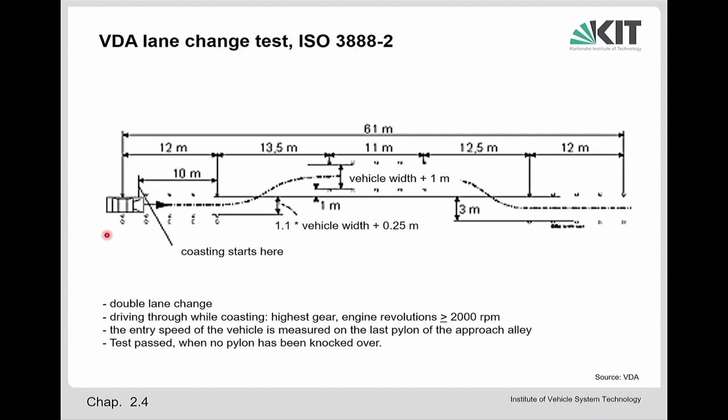Then, at the end of this, if the spring is completely compressed, there is an end stop. This is a rubber element. If the end stop gets in contact with the car body, the deflection of the wheel stops abruptly, which gives an extra force input in vertical direction.